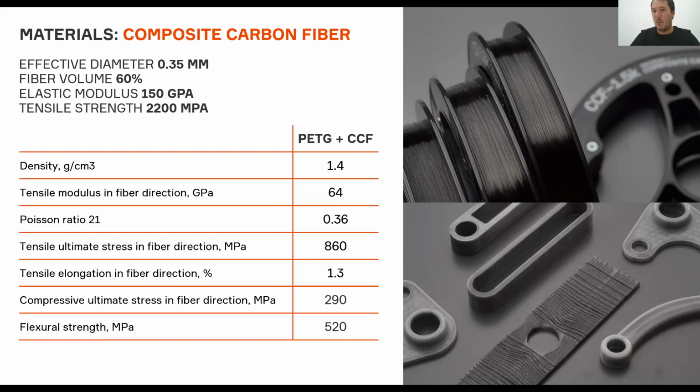So there will be one model in the slicer that is used as a base model. Then you can import another supplementary model together with the base model, and there will be a possibility to create so-called layer masks, so that the fiber trajectories could be defined based on the Boolean or on the intersections of the two models.